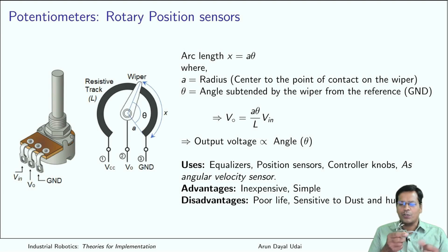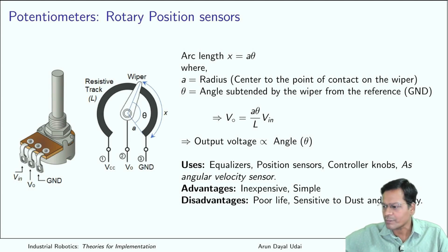In case of an optical encoder, it was 5 wires. One is casing ground, and then voltage, ground, and phase A, phase B. Sometimes an index is also there. So it may have 5 or 4 wires, but this always has 3 or 4 wires because of this shielding ground.